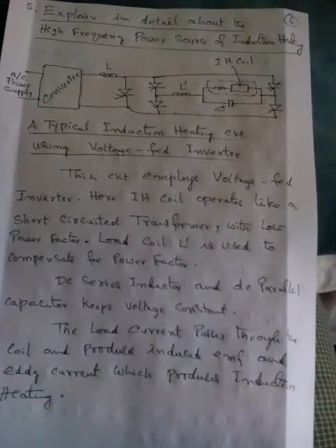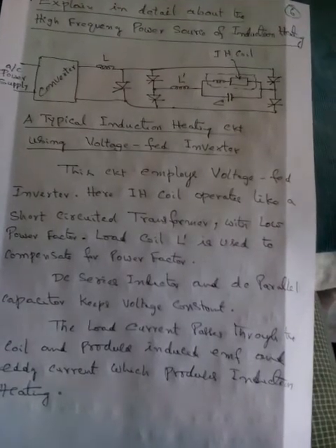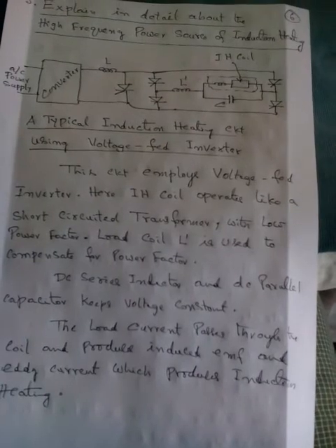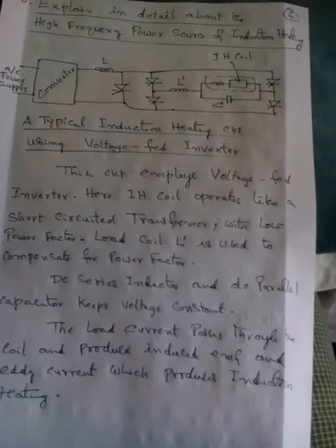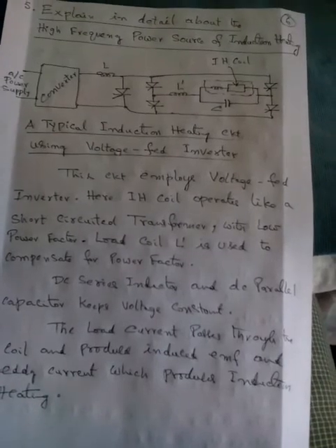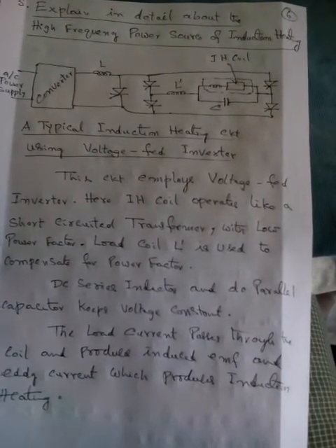They put the conductor to be heated in that induction coil. There is a provision for putting conductors in that induction coil, and a large number of conductors can be heated. Mostly it is used on a large scale for the surface hardening of steel rods.